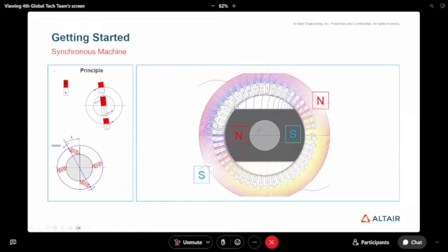Then we can fight against the inertia of the rotor, and the polarity created on the rotor by the stator field lets it catch up, since we are moving slowly. The north of the rotor has the time to catch the south of the stator, and then it will move like this.